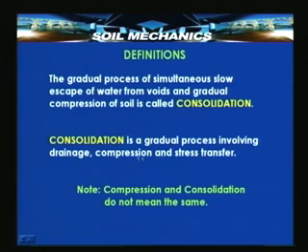And another way of putting it is, consolidation is a gradual process involving drainage, that is expulsion of water, compression and stress transfer. This is a new word that I have introduced. When you apply a load to a saturated clayey soil, ultimately the load has to be taken, otherwise the building is not going to stand. Where does this load go?